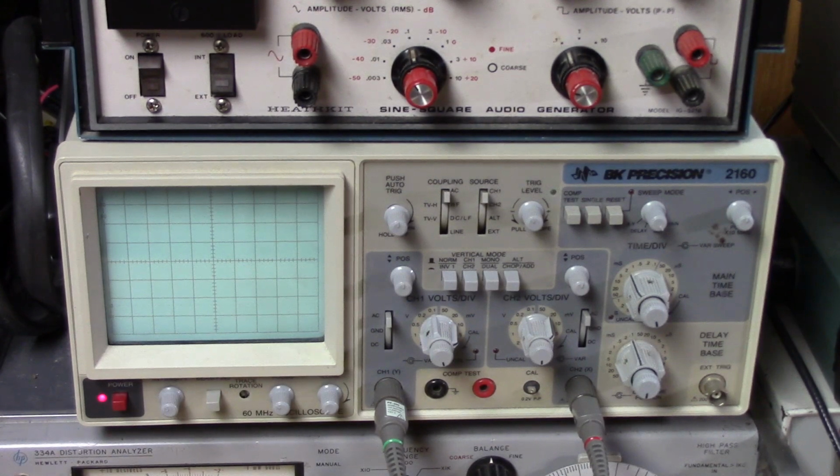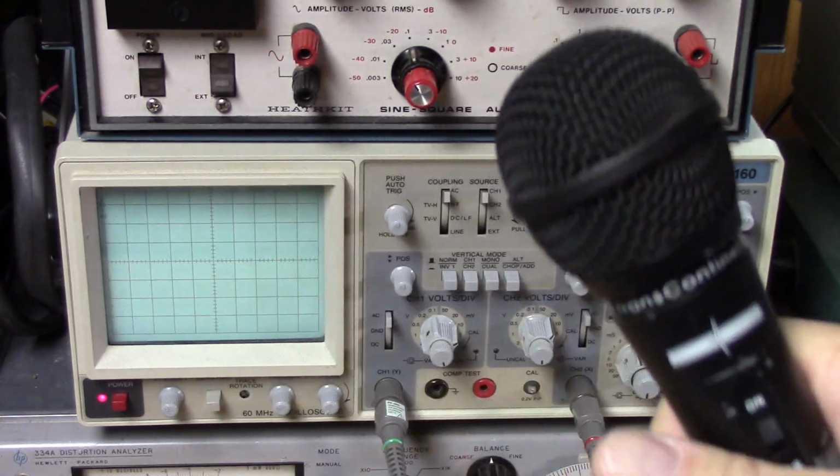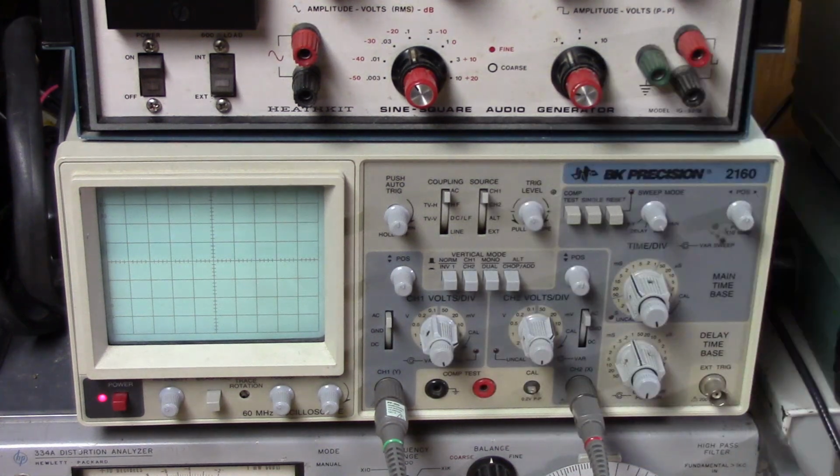So, let's talk about polarity of speech. Now, some of those guys were complaining that I didn't have a lot of positive modulation. Now, this is an ordinary hand microphone. It's a dynamic mic. Has an impedance of a few hundred ohms. I'm just going to put it straight into the scope. 1, 2, 3, 4, 5. Hello? 1, 2, 3, 4, 5. I think you can plainly see that this microphone has a positive polarity to my voice. It is correct to my voice.